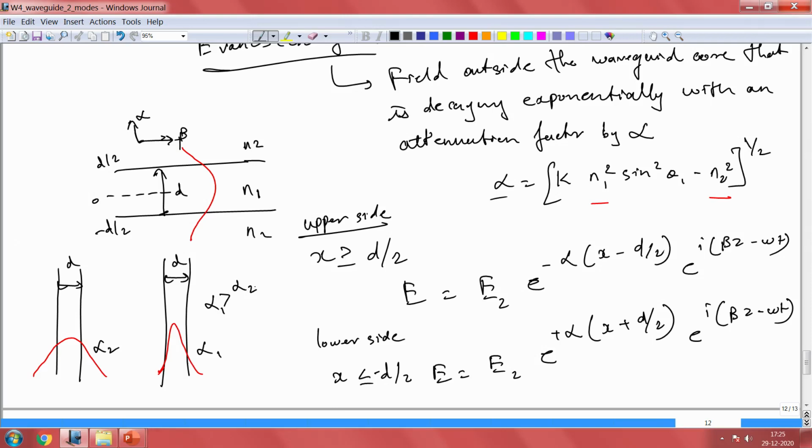So, how did we achieve this? This is achieved by looking at the refractive index contrast, n1 and n2. We can have refractive index n1 and n2 here. When the refractive index n1 is much greater than n2, you get very high confinement. That means you have very strong decay, so the light is not allowed to go out. It is pushed inside, but in this other case n1 is just greater than n2, it just meets the criteria.